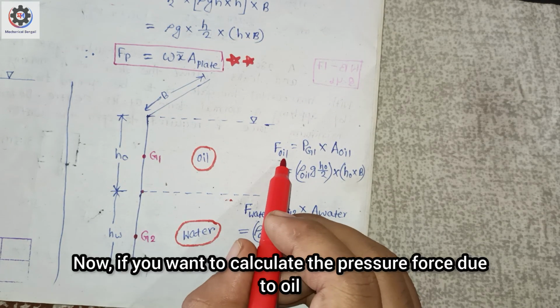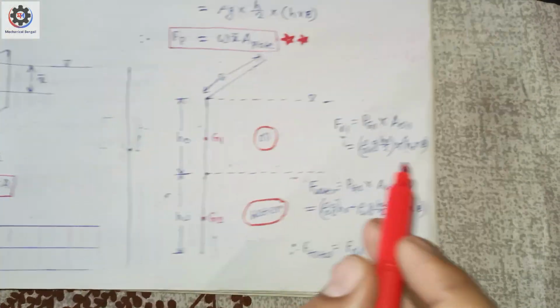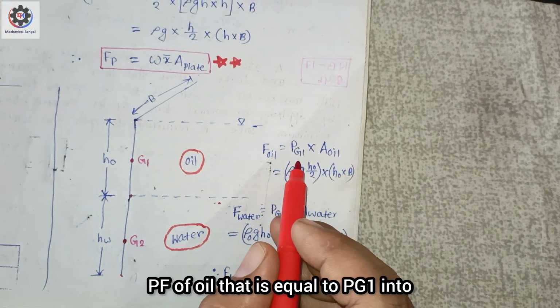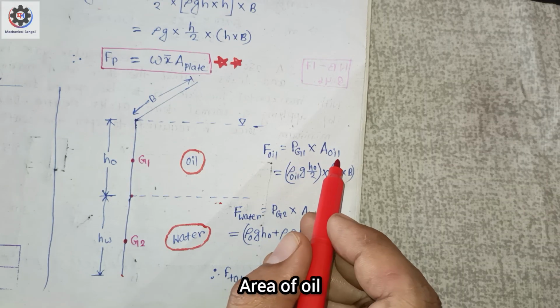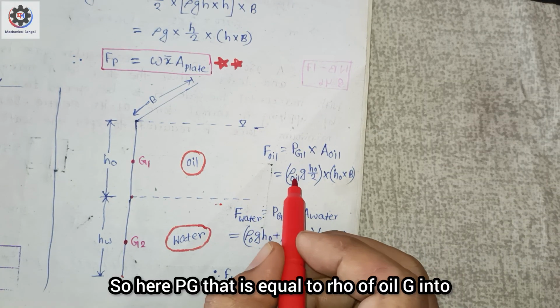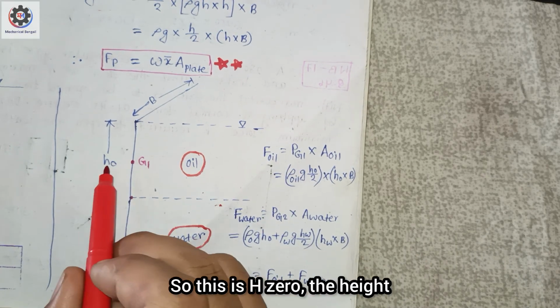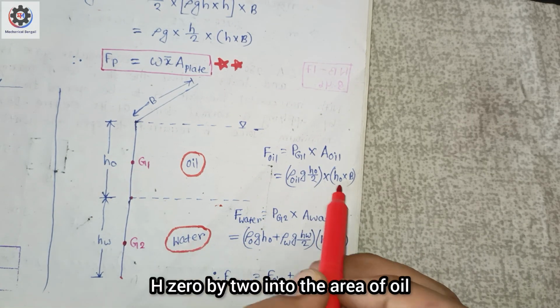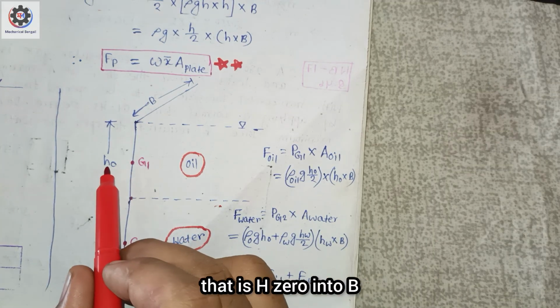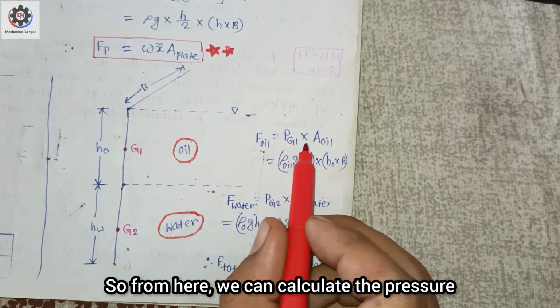Now, to calculate the pressure force due to oil, that is pg1 into area. So the force of oil is equal to pg1 into the area of the oil plate. Here pg1 is equal to rho of oil, g, into the distance h0 divided by 2, into the area of the oil plate, that is h0 into b. So this is the area of the plate. From here we can calculate the pressure force due to oil.